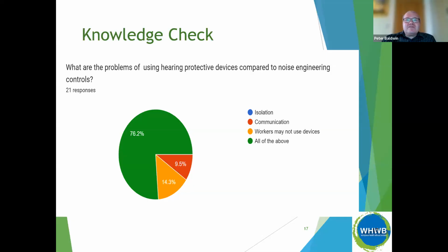So this is the question about what the problems are with using hearing protection devices compared to noise engineering. If you're looking at noise hearing protection devices, you can end up with isolation issues because you can't feel, you can't talk to people. Communication with people might be an issue because you might have to shout so they can hear what you're saying, and they may not use the devices.